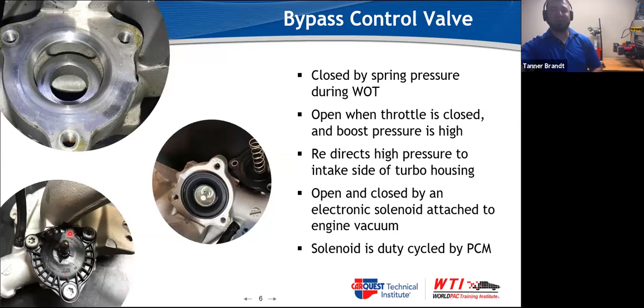As you see, we're on this side of it because you see the oil here. That means that if this were to try to pull open, there's liquid here, so we no longer can move this to the open position because it would be trying to compress liquid. When that happens, you can end up with turbo surge because that valve is no longer working.